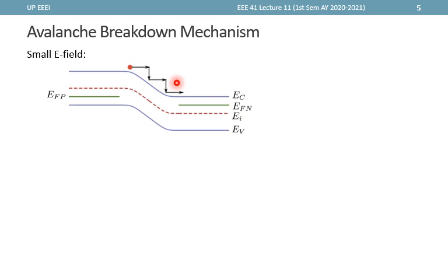However, what actually happens is that this electric field here accelerates this carrier, this electron, and at some point the electron will bump into the crystal and it will lose some kinetic energy, and that kinetic energy is transformed into heat within the crystal. So the acceleration and the transfer of kinetic energy happens in multiple steps until this electron gets to this point.